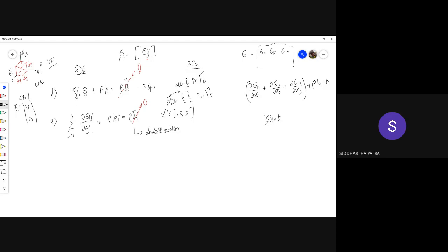For example, in the cantilever beam, at the fixed side, you'd mention that the displacement and the rotation are zero. So you know those values, and those values happen to be zero. If you classify the u vector at any given location as w, theta, which we did with beam elements, then u bar for you should be the vector of zero, zero, constants. That's all I'm saying. Similarly, this t bar is also a vector of constants that you know.